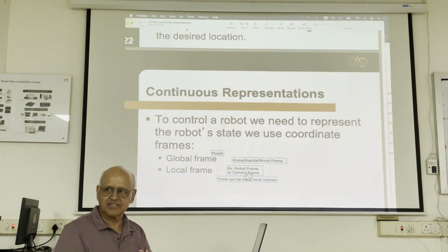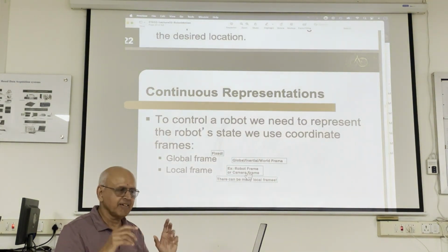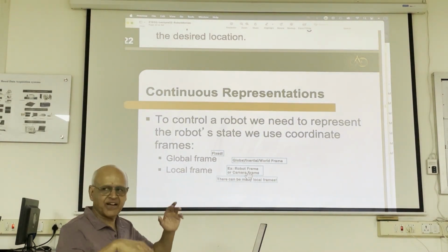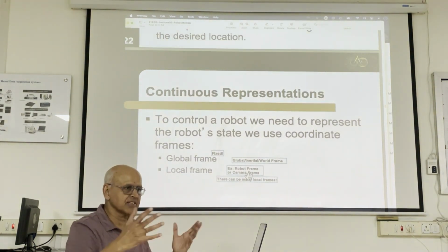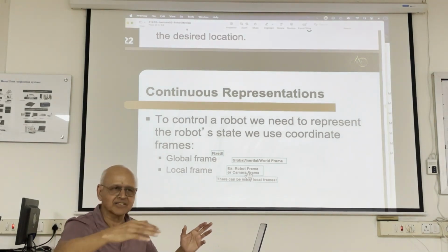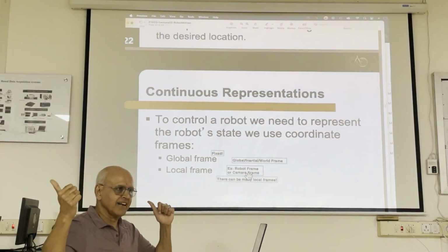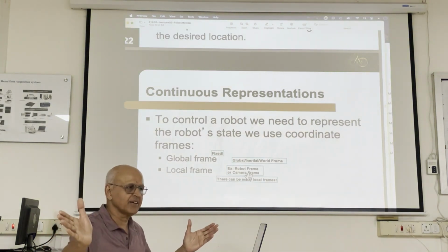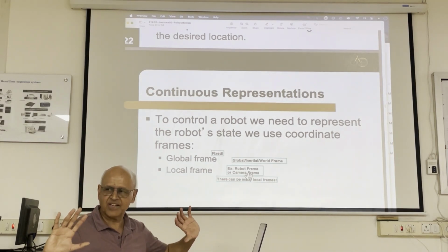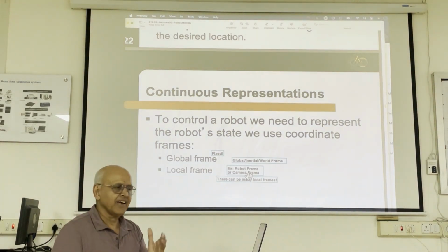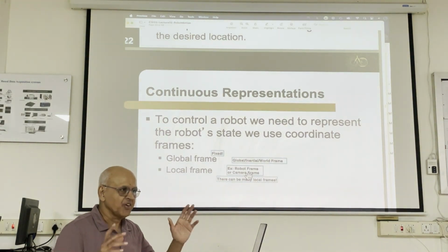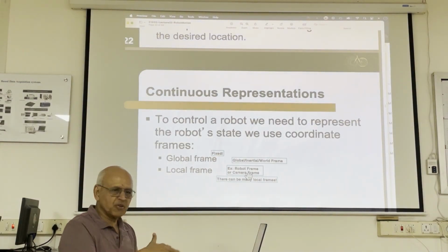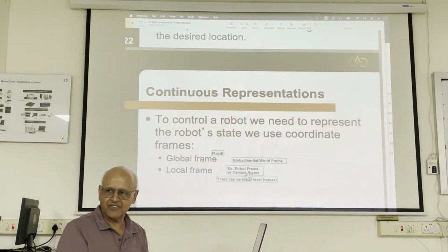Just think of a simple task. The robot is in a hurry. They mounted 4 cameras on it to build a map of the environment. So it's looking every which way and it's driving around, right? Otherwise, how do you figure out the map? You have to drive to all the corners. Do you realize that you can't just join all these maps together because they are different points of view? Somehow they have to have the same alignment. For that, not only do you have to first put them on the robot frame, but that's not enough either because the robot was pointing at different parts of the environment.